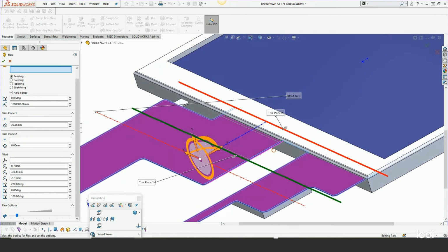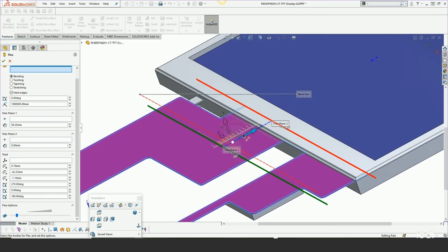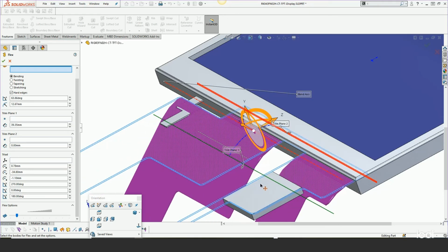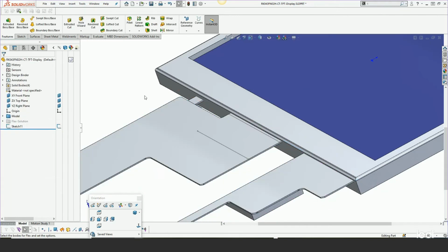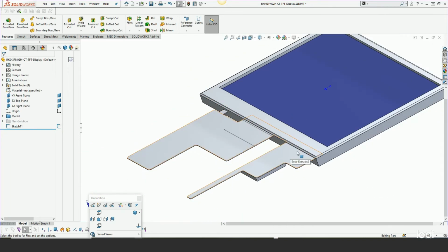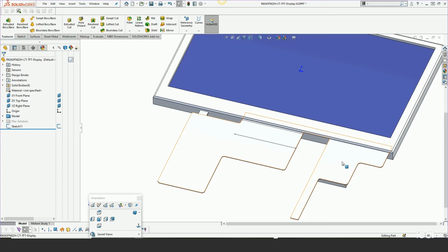But what I'm trying to emphasize here is that if we were to bend this, it's going to be bending both of these flexes at the same time. So what I need to do before I do this, I need to split these apart or go back into my features and separate these as models. Now, sometimes it's hard and there's not a good reason, or it's preventative from being able to change the feature.